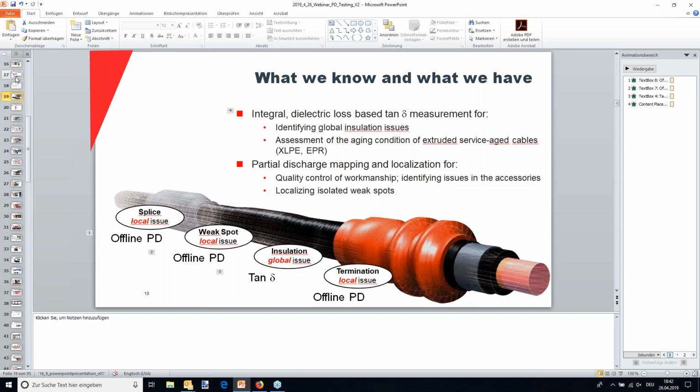What cable rejuvenation means is they inject a silicone fluid that jellifies and solidifies the insulation again and tries to bring back some of the dielectric strength. Now, this curing process can take quite a bit, months to years. You typically say at least a year, sometimes even more. And in that time, I'm telling you, if you measure the tan delta during that time, you go out of your mind, because you see insane changes, weekly changes, because there's a chemical process going on in that cable.